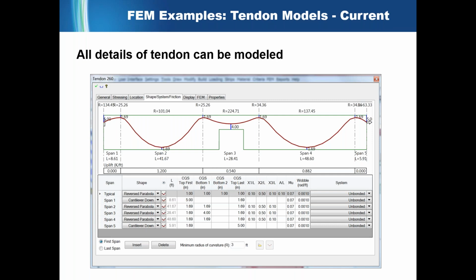Another thing to note is that the way we specify, let's say, or lay out tendons, it's with a CG offset from your extreme fibers at the top and bottom at mid-span. So in a case like this, it's really nice if your slab section or beam section changes thickness, which of course happens over the course of your project design, that the intention of your profile will be maintained even as the slab section or beam section changes, right?